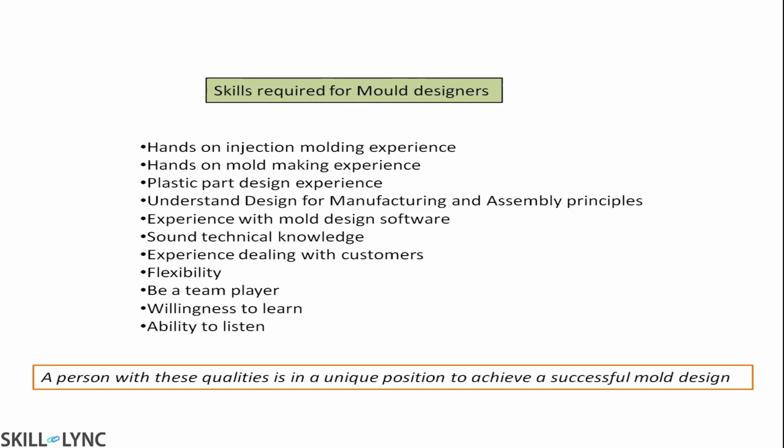What I am starting with is injection molding experience, which we need, and mold making process experience. Some tool makers do mold making: how the core and cavity are assembled, how the slider is assembled, and all the processes involved in tool room activities. And plastic part design experience is nothing but how the plastic part is designed from the B surface to the A surface, and how the bosses are mounted on the plastic parts. I will teach you these stages later in this seminar.